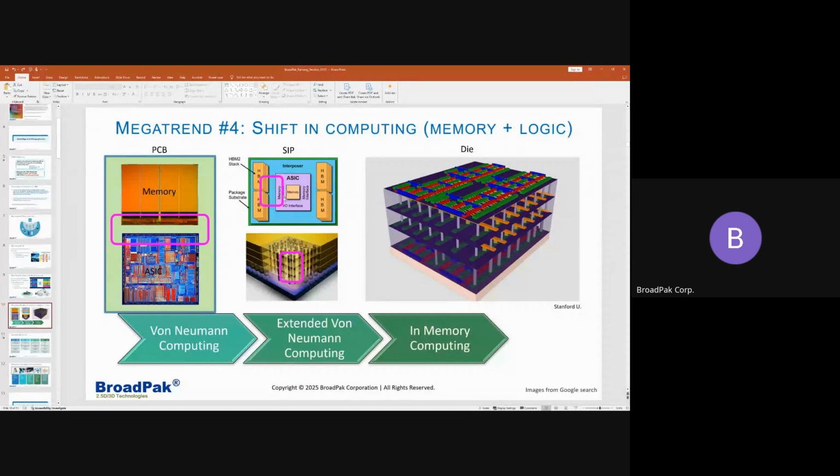So now you have your device here that is going to communicate with the other memory component, which is mounted right next to it on the same package, meaning we're going to shorten the communication pathway between the logic and the memory. That's where things are now. To increase the memory bandwidth, this is the high bandwidth memory. You'll notice that the DRAMs are being stacked and connected with TSVs right through them.